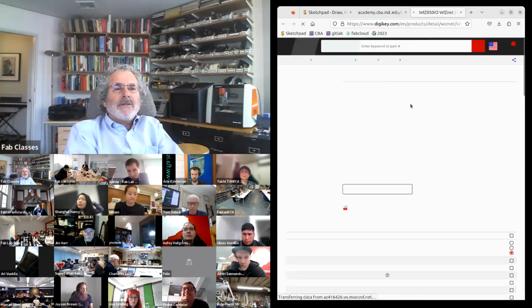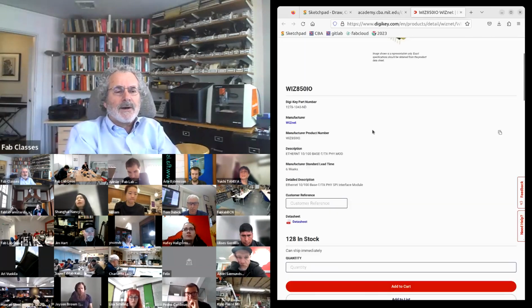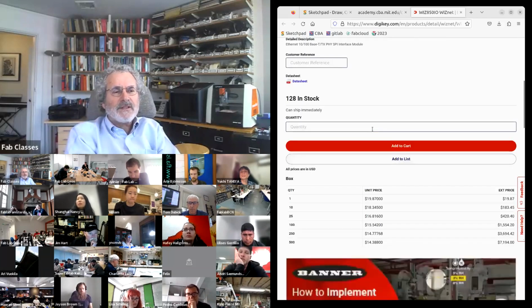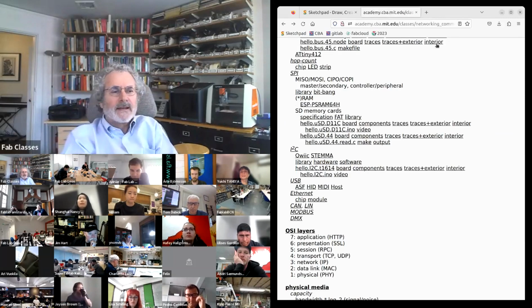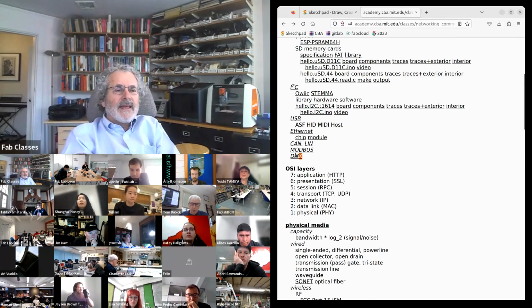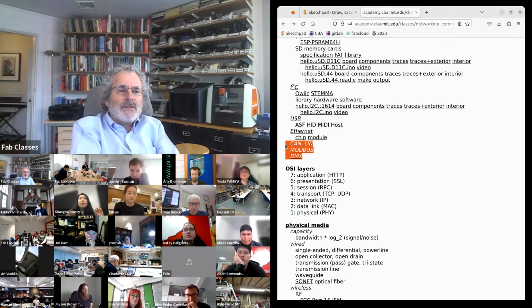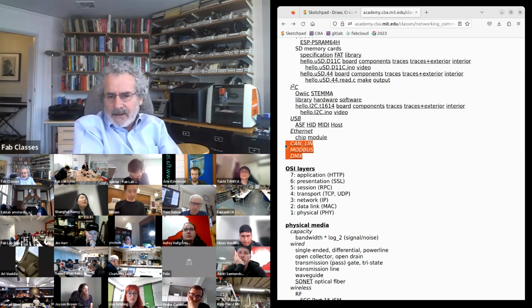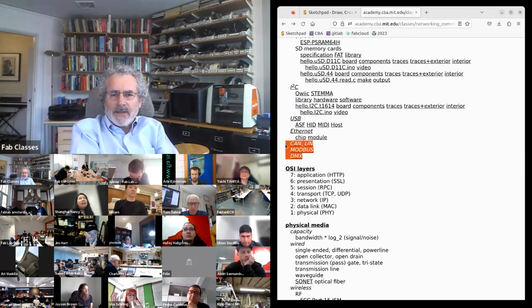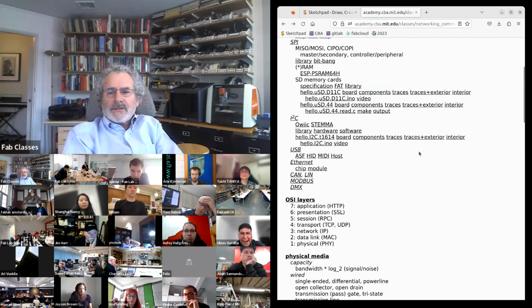Ethernet is less common now. If you want to speak Ethernet, the usual way you do it is this is a module. These are $10, $15 that speaks Ethernet and then has a protocol. And I'll talk about the protocol stack to talk to your processor. Then CAN, LIN, Modbus, DMX, those are all networks that are used in cars and industrial systems and lighting. I wouldn't pick them from scratch in your own project, but there's good support if you need to talk to them for something else you're talking to. So those are all wired networks.